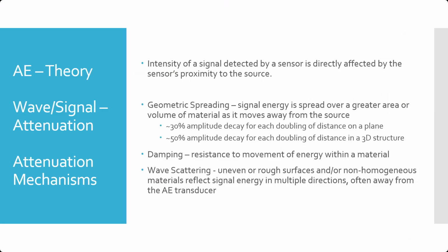So where you have 2 different materials, it's where we put the probe on the part. We have to couple it using gel, right? Otherwise, the sound doesn't transfer very well because we have an acoustic interface, a poor acoustic interface or a barrier. So if you have a material that's non-homogeneous, what's a non-homogeneous material? You can give me an example. You don't have to define it. What's the non-homogeneous material that you have all worked with extensively?